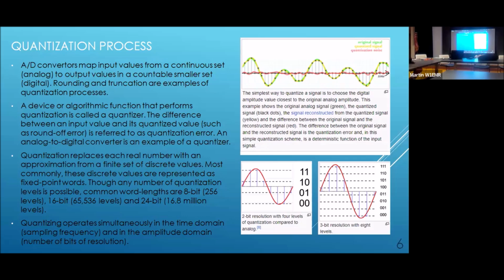And the good news is you can build such a chip. The bad news is there's no way you're going to get 32 bits of resolution. 32 bits of resolution implies that you could get a signal to noise ratio of 190-something dB. That isn't happening. Your thermal noise and the maximum voltage that you can actually work with make that much lower. Okay, and that's going to be something we have to talk about. So all these audio freaks, I think they're kidding themselves.